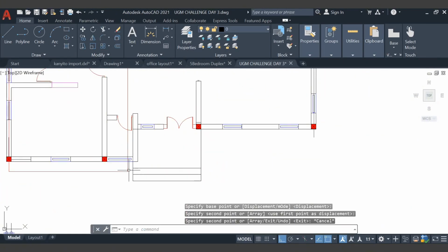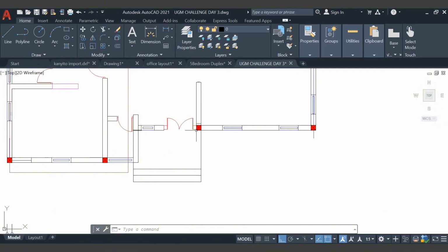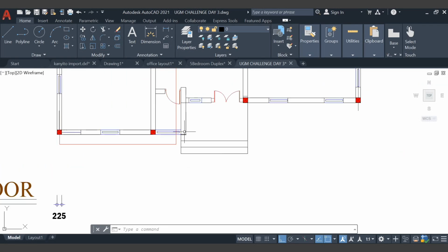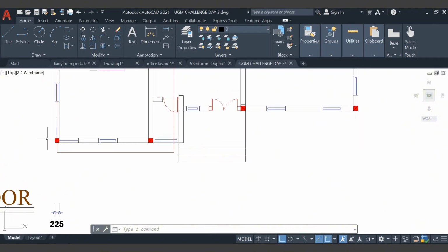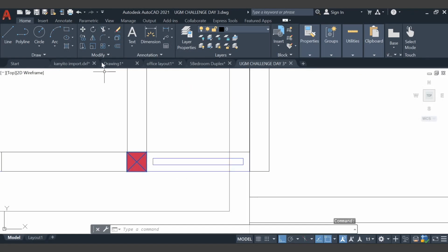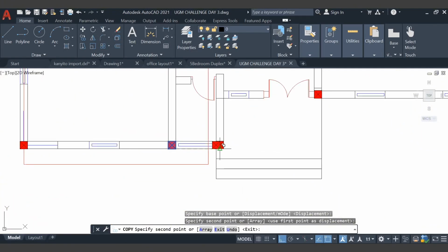We could actually decide to place one here also. So we could have the shape of the building, which is this corner shape over here, or we could decide to move this guy over here. But if we do that, we know that we've gone against our rule of 5.5 meters, so we would need to really pay close attention to this beam because it might fail. So if you want to be too safe, or if you want to be safe, you could place another one here.